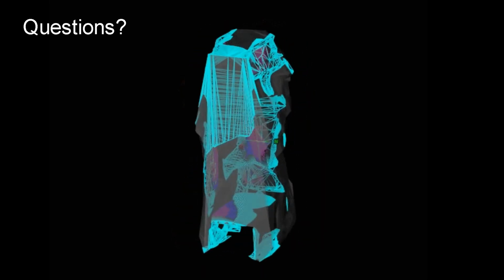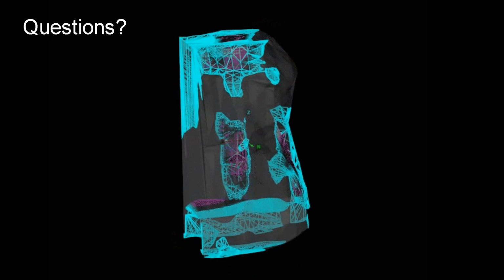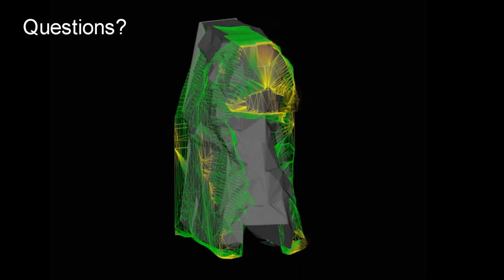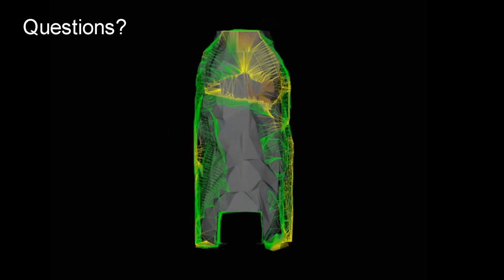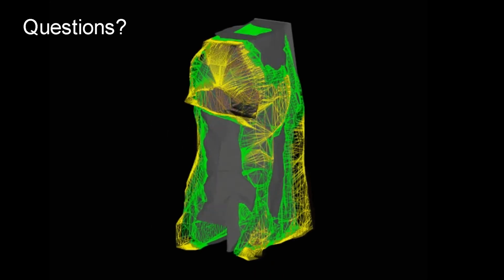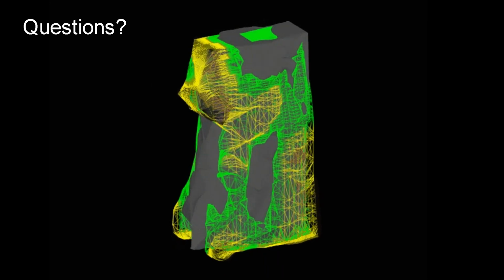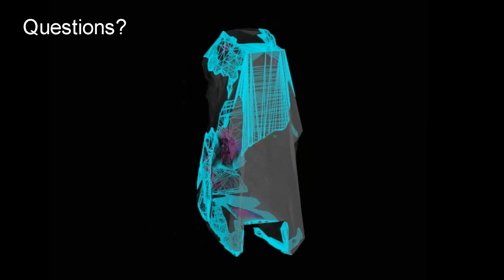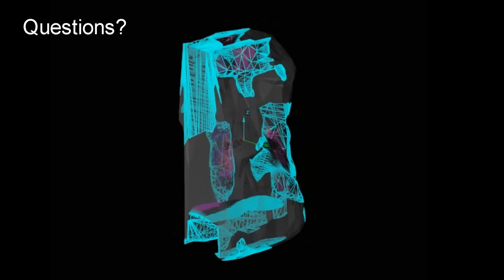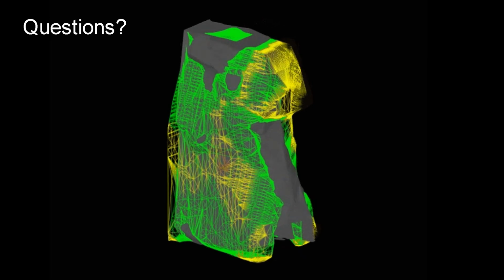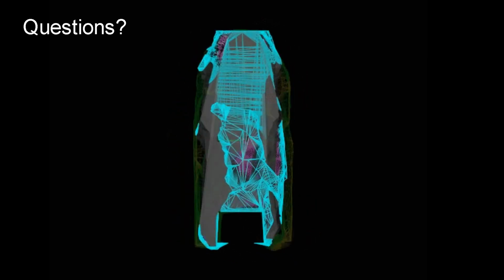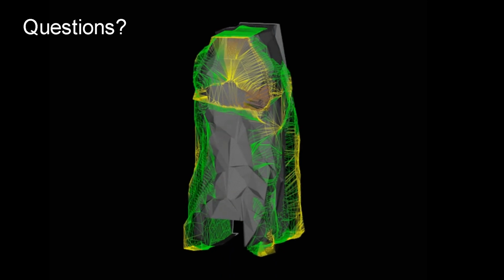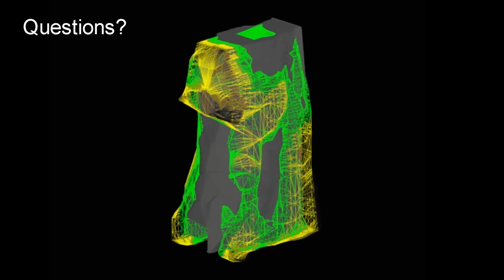This might be as simple as having to adjust the fan operating point. Of course, that would come with a cost if we are running the fan, consuming more electricity, or perhaps we need to install more bag line to get fresh air to the face. If we're finding that, by not maintaining that smoother surface, or not practicing good perimeter control, that can really add up over the course of 1,000, 2,000 meters or feet, depending on where you're working.